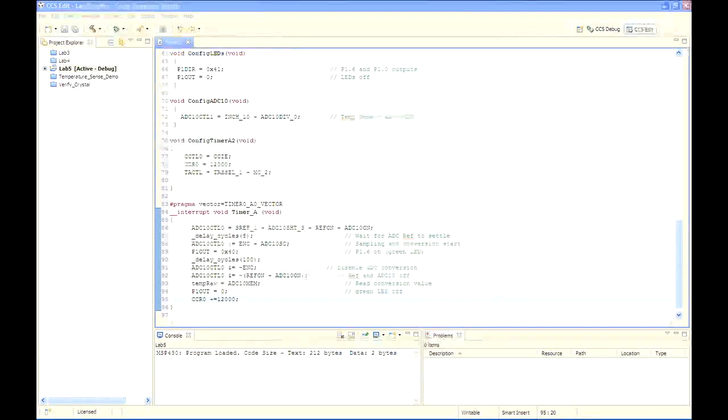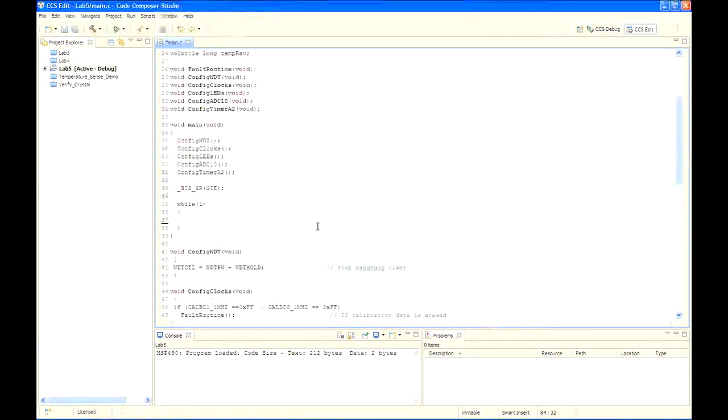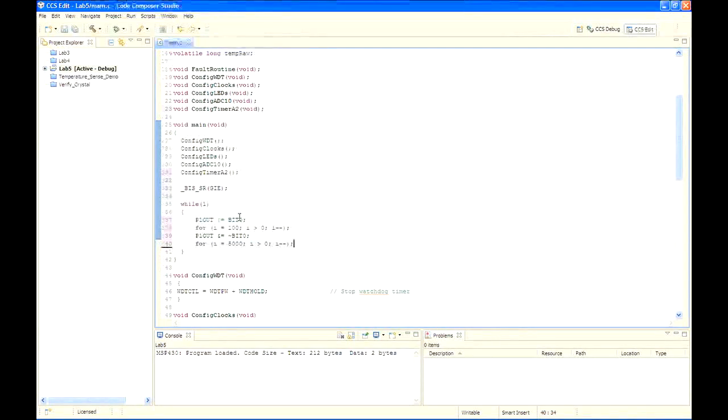In step 12, we need to have some code running in order to be interrupted. In reality, we don't. You could have a while loop sitting there with nothing in it that would run, but I think it would be more interesting to actually have something running. So what we're going to do is add a little while loop with some blinking LEDs. So take the 4 lines of code shown in step 12 and paste them into your while loop.